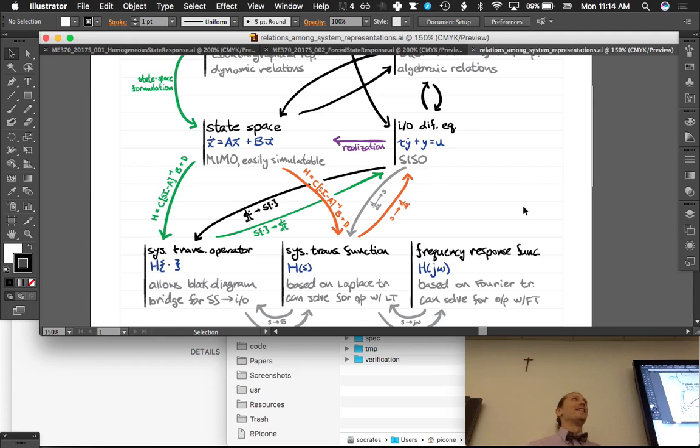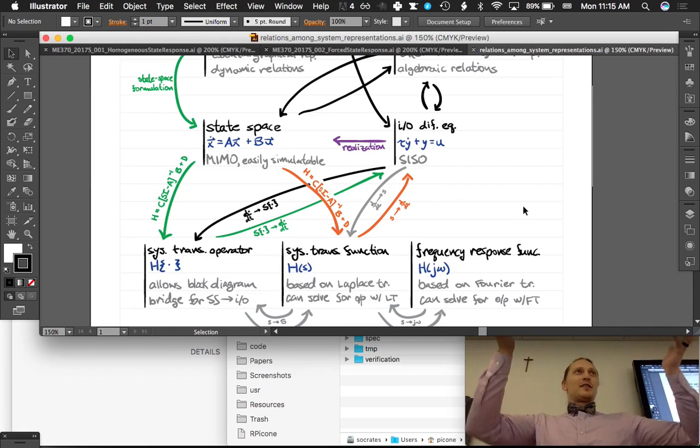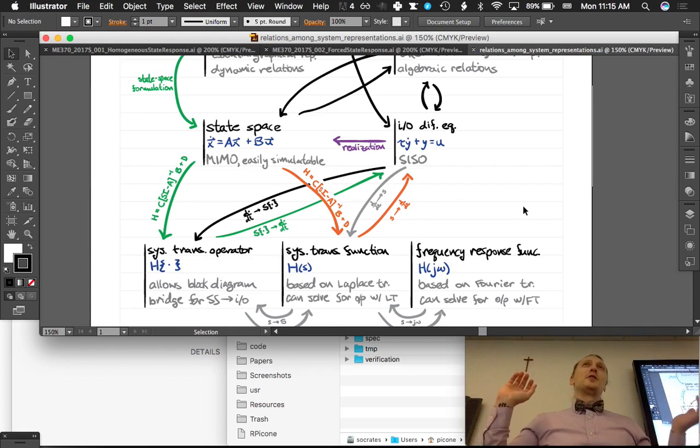So in there's a float, and that float, when you have water coming into the tank, rises up, and if it's connected to a mechanism that stops the valve that's spraying water into the tank when it gets to a certain height, you've got yourself a control system right there. And if it doesn't stop it when it gets to that height, you've got problems.